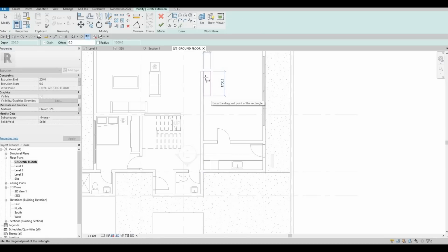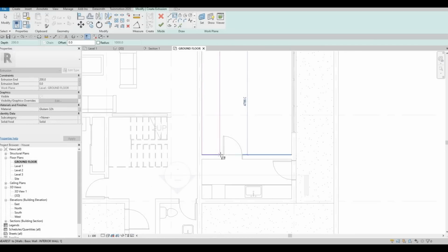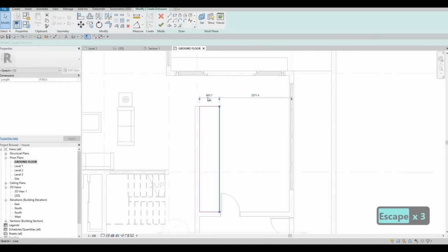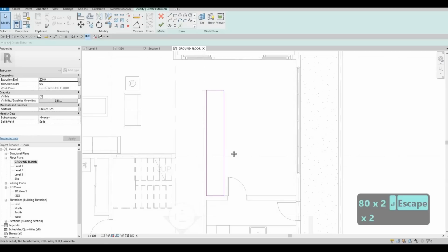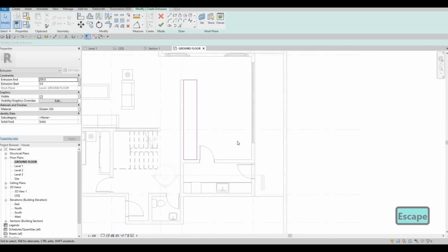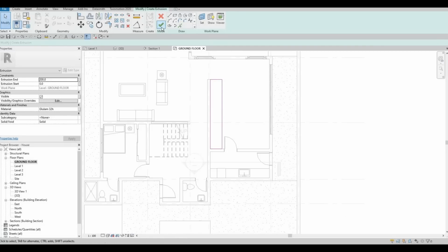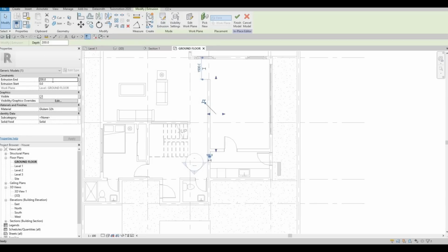and then we could add a wall right here so that it's covered right there. So here I want it to be at least 800. I think 800 is good enough size. And then here I'm gonna do this separately for sure. And then here I'm going to click on finish. I want it to be at least 875 height, extruded.